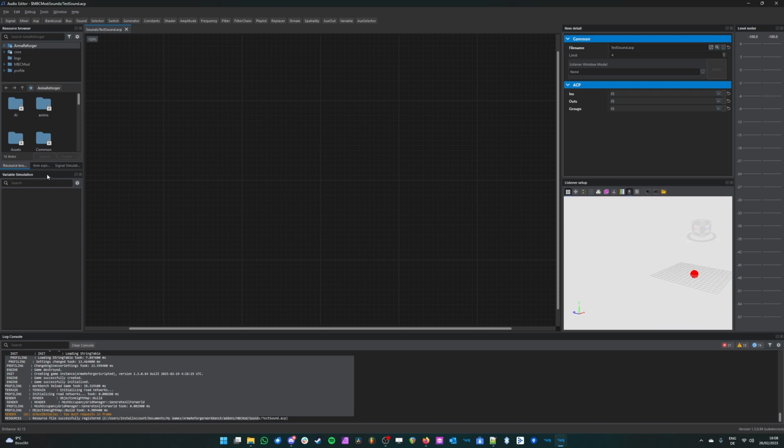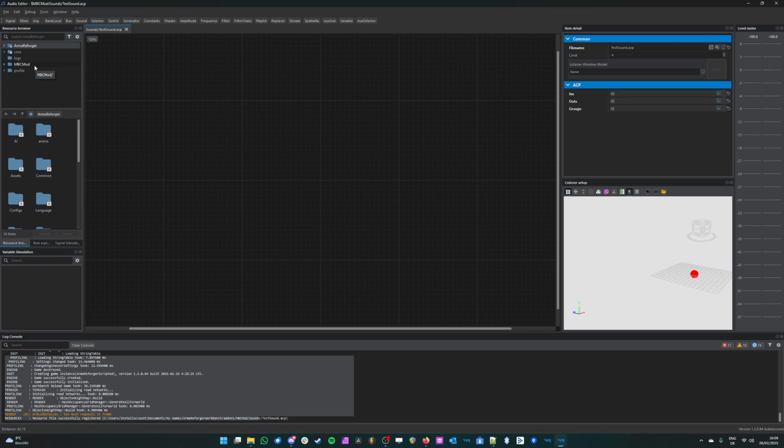Okay, so how do we set up a sound? First and foremost, if we want to use a completely new WAV file anywhere, and by the way, Enfusion only takes WAV files, no MP3s, very important to know. I have a random footstep sample here, for example. If you just drop it in a folder somewhere, you might think, oh, I'm good to go, I can use it, I can even double click on it, and it will play back the footstep sound.